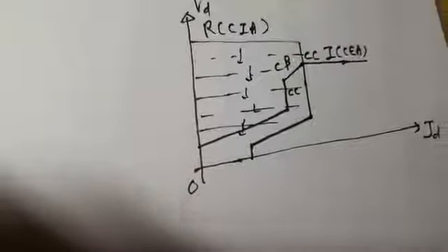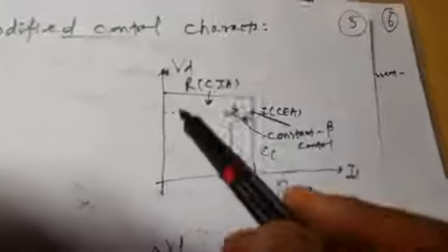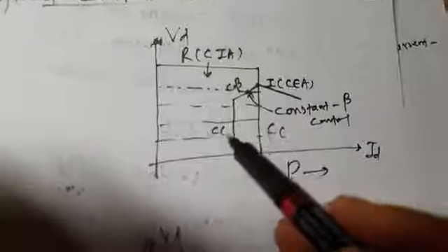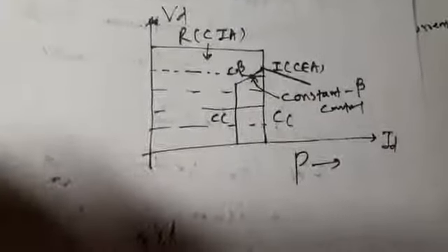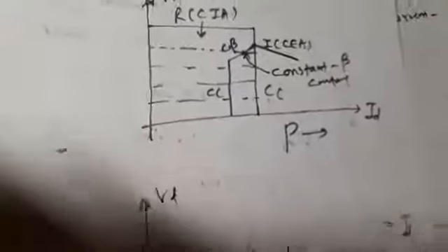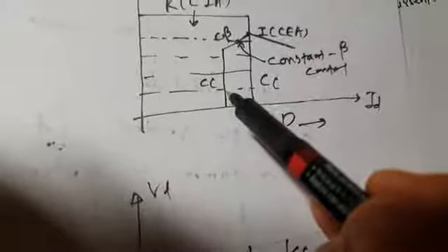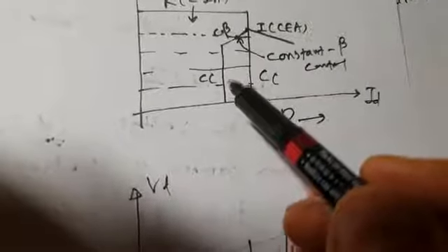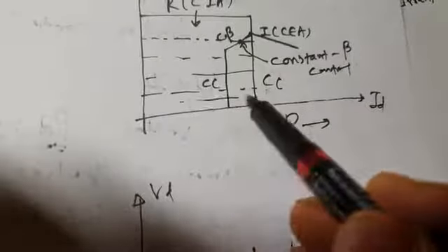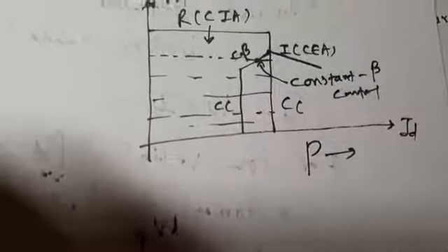Then, for making a certain amount of power flow, the current in the link has to increase. Because the link voltage has collapsed, your controller will automatically try to increase the current to maintain some amount of power. Otherwise, under extremely low voltage conditions, there may be almost no power in the link. It will be very difficult to keep some power flowing in the link.